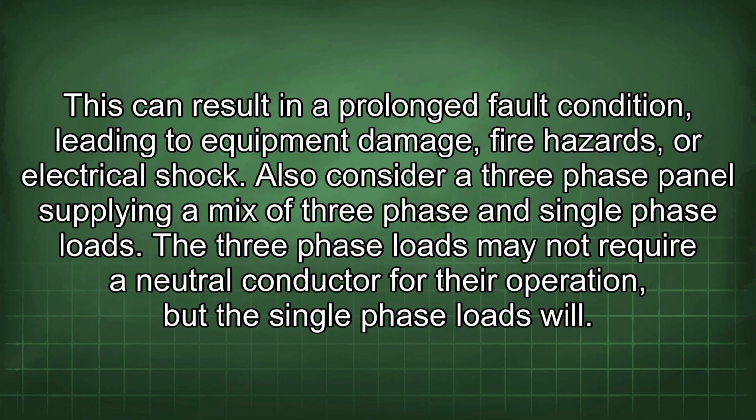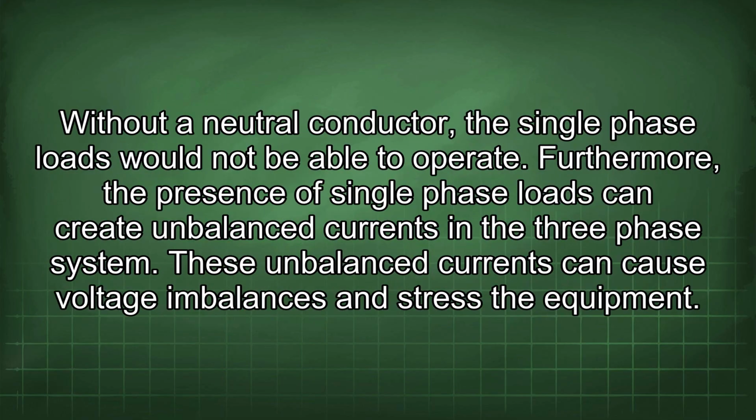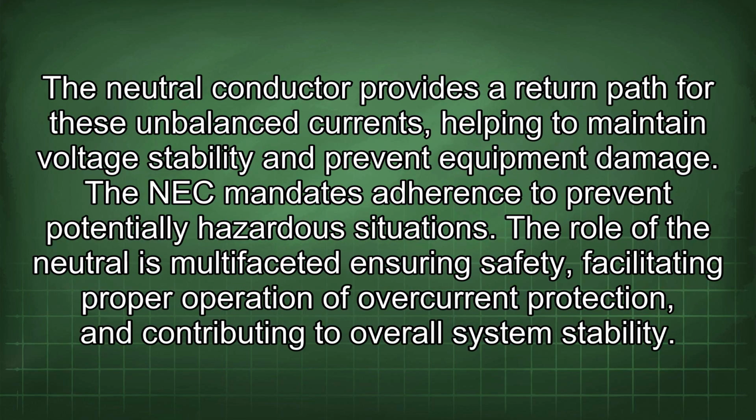The three-phase loads may not require a neutral conductor for their operation, but the single-phase loads will. Without a neutral conductor, the single-phase loads would not be able to operate. Furthermore, the presence of single-phase loads can create imbalanced currents in the three-phase system. These imbalanced currents can cause voltage imbalances and stress the equipment. The neutral conductor provides a return path for these unbalanced currents, helping to maintain voltage stability and prevent equipment damage.